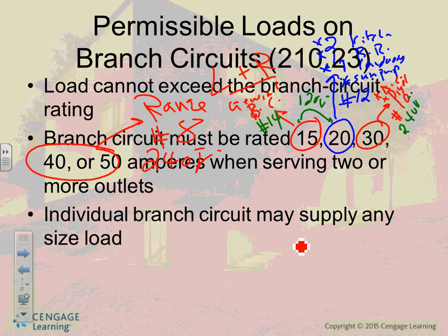Now, if it's in a commercial, guys, anybody know what we drop in a commercial? The 15 amp circuit. Typically, can you use it? Yes. Good idea not to use it. So when we do commercial industrial, you start with number 12 wire and 20 amp. Lights or receptacles. Done. That's your rule. In a dwelling, we use 20. In commercial industrial, we drop that 15 circuit.